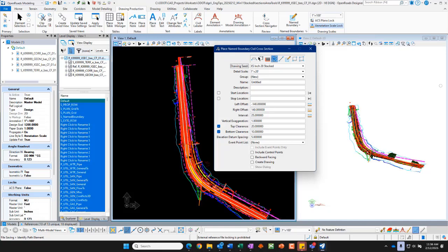We can do the same thing, but the steps are slightly different with OpenRoads. The reason the steps are different with OpenRoads are mostly because the graphics for the civil data is not drawn into a cross-section design type model. They are referenced into drawing type models.